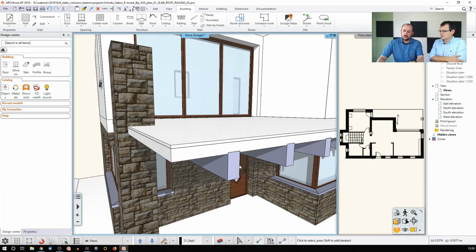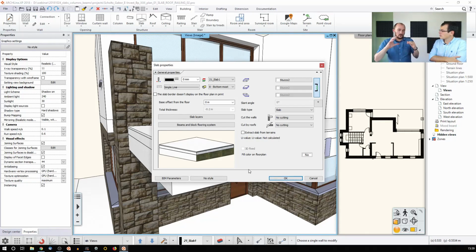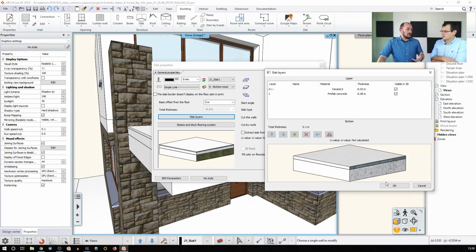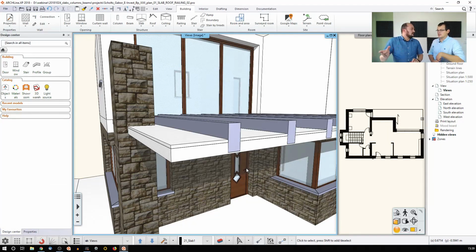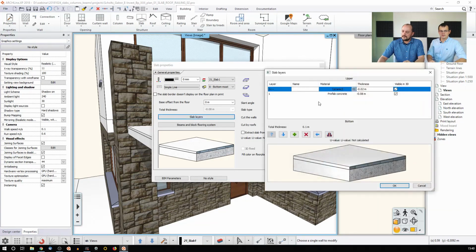There is also another way, which I think is much better, and it describes how this whole inheritance works inside the structure. If I'm erasing that layer, so instead of disabling it, I just select it and erase it, what happens? Should the beams disappear because I have erased those layers, or do they just move somewhere else? Actually the latter will happen. They automatically jump to the following layer. So the software won't destroy what you have created. It just tries to find a better position. Now it's not good yet, so I further edit it and say, okay, let's erase this as well.